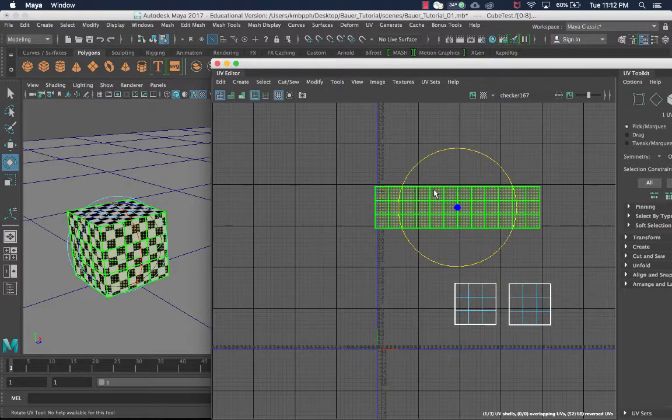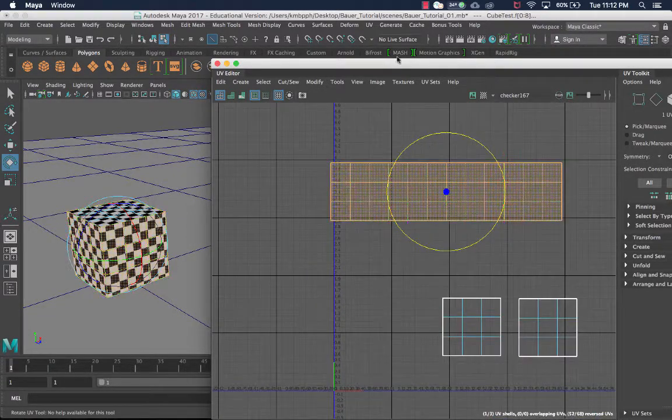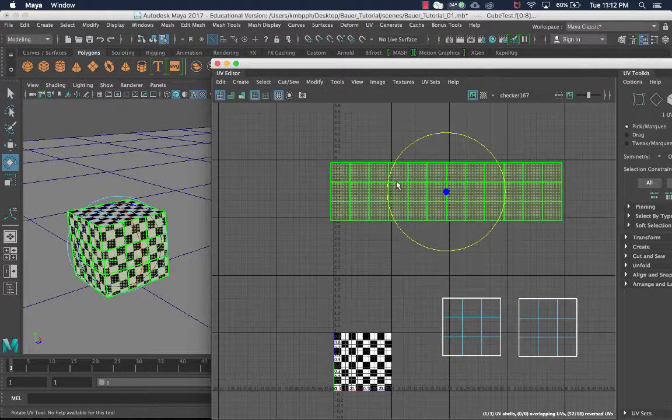Okay. So like I mentioned before, in order for me to actually paint textures on top of these, I need to take that UV snapshot. And in order to take that UV snapshot, I need all of these objects, all of these shells, to be in this first little grid. If I turn that file back on, you can see my checker pattern down here. I can now move these objects and put them down inside of that little checker pattern grid so that I can make textures on them and get something going.